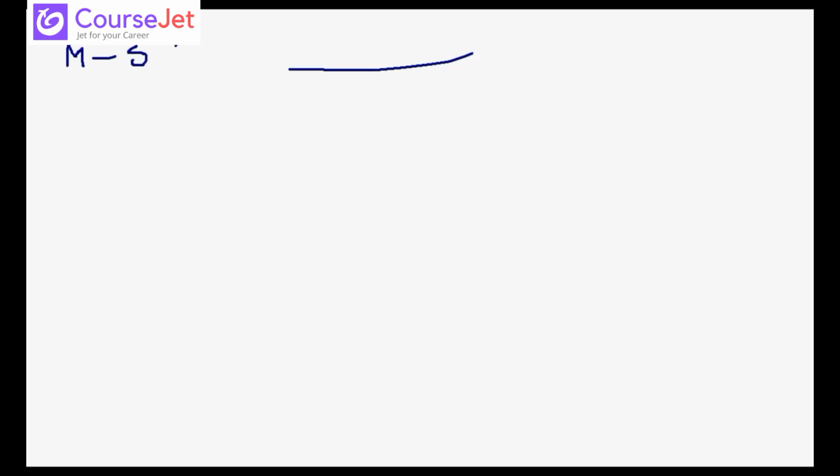Okay, the slave's address is something, we will take some random address. I am saying 1101 1011. Sorry, 7-bit address, right? So my master is going to send suppose something like 10101010, which is AA. I'm saying some random data. Actually we will not send AA, but simply we are sending some particular data.